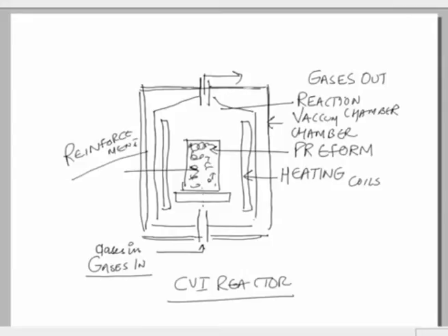Because we are talking about a composite, the reinforcement is the fibrous preform, and the deposition that is taking place, the solid material that is getting deposited in the porous spaces or on top of the fibers which are a part of the preform, that is the matrix material. So the matrix is being created or deposited on top of the preform, or on top of the fibers which form a part of the preform.